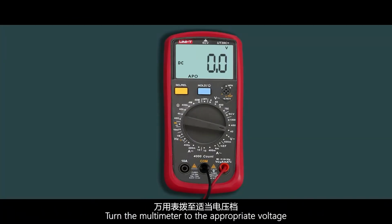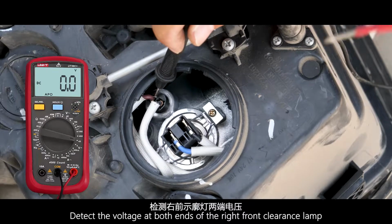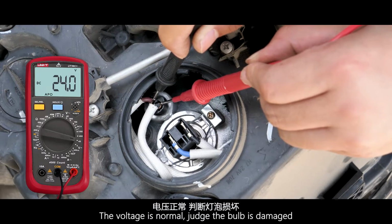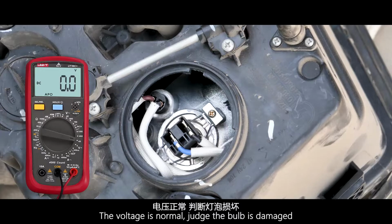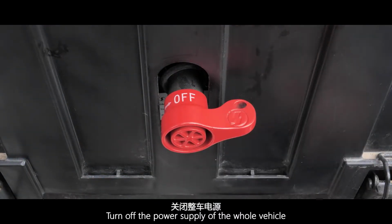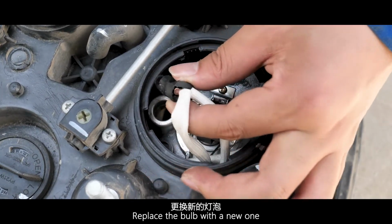Turn the multimeter to the appropriate voltage. Detect the voltage at both ends of the right front clearance lamp. The voltage is normal. Judge the bulb is damaged. Turn off the power supply of the whole vehicle. Replace the bulb with a new one.